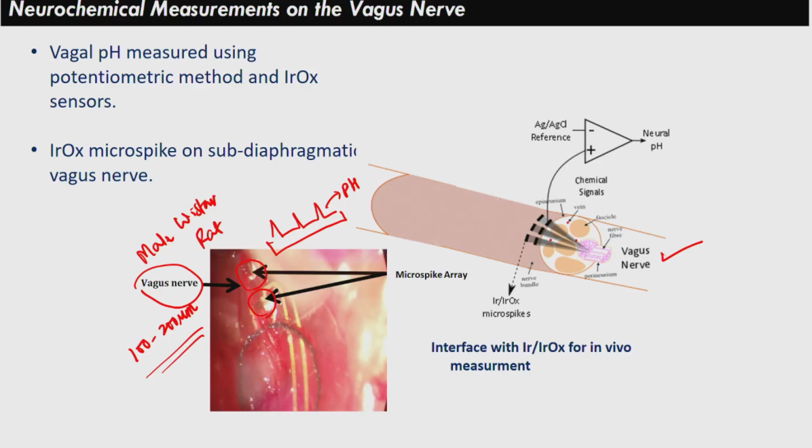Generally, when you are recording biosignals inside the body, whether it is neural signals, or you are recording from a certain muscle, what happens is the EMG and the neural activity share the same bandwidth. So, you cannot actually use filters to isolate EMG or non-specific activity from the neural activity.